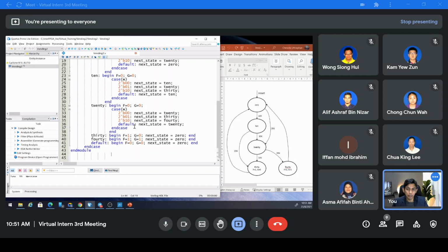This is called synthesizable code. Remember, when you code in Verilog or VHDL, you should know exactly what your code will be synthesized to. If you don't have this, when you compile your design, you will have many warnings, because Verilog will automatically assign the value for you.